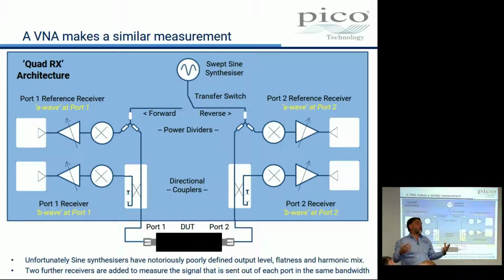It'll be a 1 megahertz signal of the same amplitude as the signal that is being received. So the signal being received is this 3 gigahertz signal, but we've mixed it down to what's called an intermediate frequency, and we've made a megahertz signal that represents the amplitude.